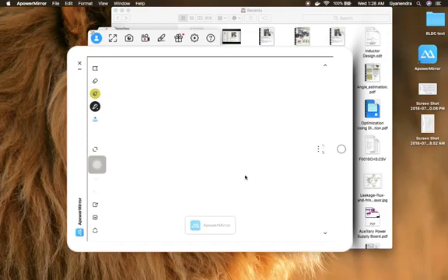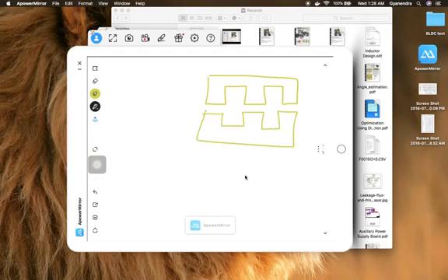So we have this E core, and this is your length of air gap that needs to be introduced. The cross-sectional area for this is A. I'm assuming the cross-sectional area of the outer limbs is half, and we will be placing windings here. Let's say the reluctance of this part is R.